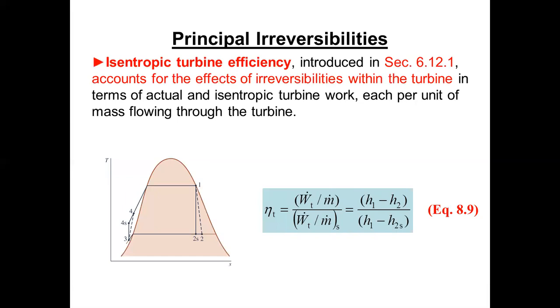Okay, and if you look at the TS diagram over there, the turbine expansion is showing saturated steam into the turbine at point 1. The ideal turbine is going to drop straight down at constant entropy, isentropic, to point 2s. So if you know point 1 and you know the lower pressure, you just go to the steam tables, and you have to do a little work in the steam tables because it's two-phase.